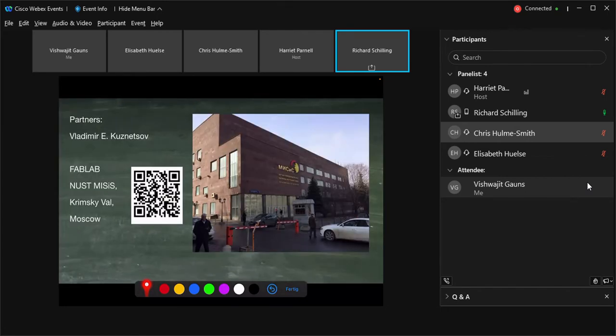and the faster you are, the less of a contact there is between the various layers, and the less of a contact there is between the various layers, the worse your mechanical properties are. So there's the trade-off, mechanical properties versus print parameters. And that's something which is, at first sight, far away from where Granta works, where the EduPack works, but it's rather close, as I'll show you in a minute.